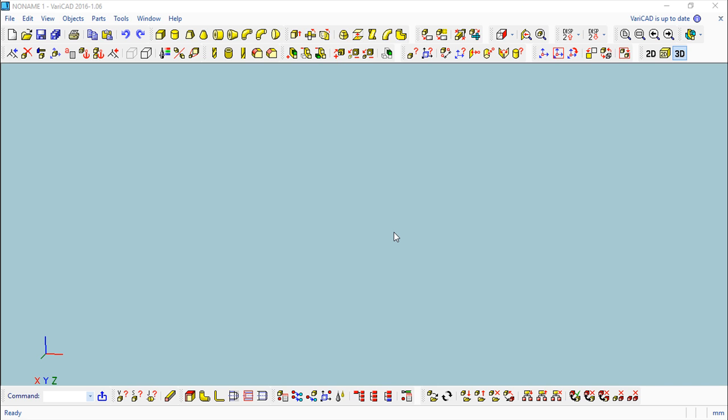If you are working in collaboration projects where someone is doing something on another program, millions of things can happen. And basically, when you import these objects to the program, that is the moment where you can have problems. So when we import, the format that is mostly used at this moment around the world is the STEP format.